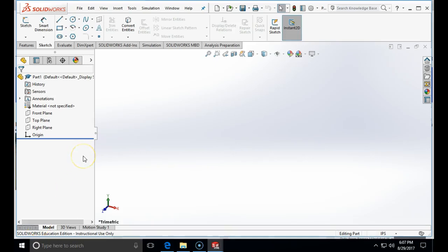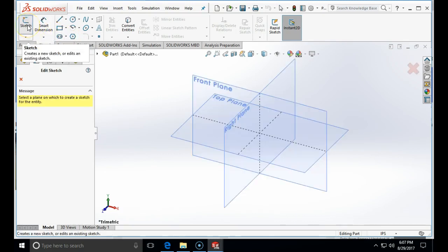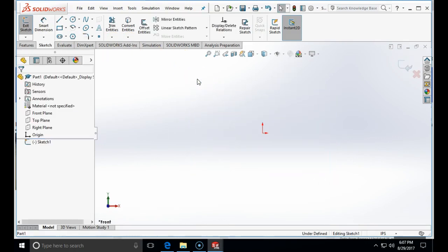So we will get introduced to the revolve-based feature. For a revolve-based feature, we need to have a sketch, and that sketch needs to contain some line which will be used as an axis. On page 151 of your book, we have a sketch that we are going to make now. You see that the sketch is distant from the axis of revolution.